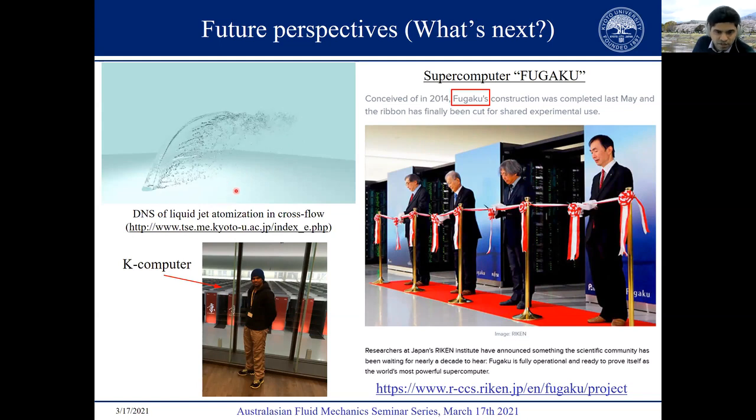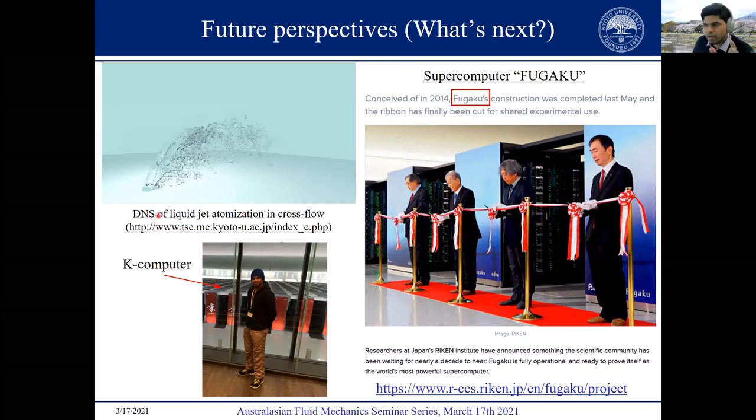Now, another aspect that is integral to these kinds of spray combustion problems and of particular interest in the combustion engineering community is the liquid atomization process. If you remember, in this study, we did not capture the entire atomization process of the spray that is injected, the n-dodecane liquid fuel. But we are working on that. As you might know, such simulations where we can fully resolve the liquid phase as well and capture the primary atomization can be quite cost prohibitive, and they have been quite cost prohibitive till now. But simulations where you can capture this phenomenon accurately, the physics of the atomization itself, are strongly desired. So far, whatever computational resources we had may not be sufficient to do such challenging and large scale simulations.